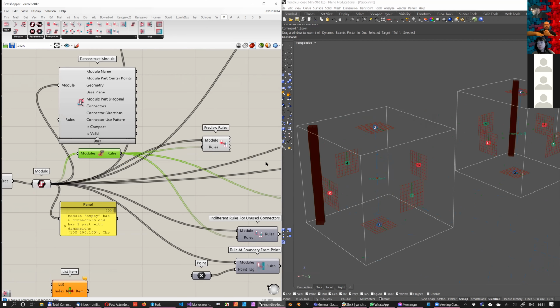And because I have to rotate everything, there is some mathematics that is very imprecise, because in computation you've got a limited number of floating point numbers. That's the discreteness that I was telling you about in computers. The computers are discrete even for the floating point numbers. Then when I rotate and adjust and place and copy, I lose precision, and even though the points that I'm checking are in the same place, they are just very slightly moved one against another, and it gives me a bad result.